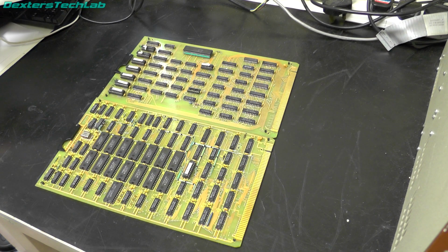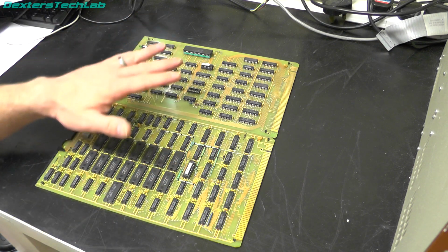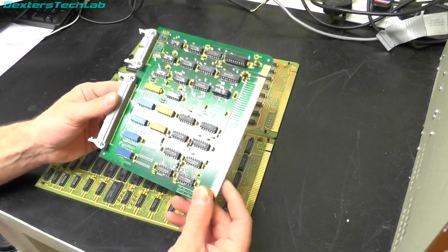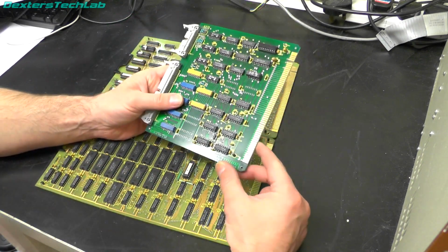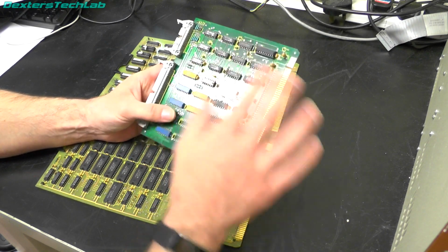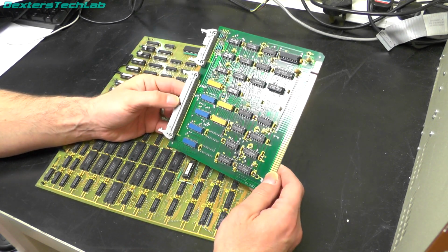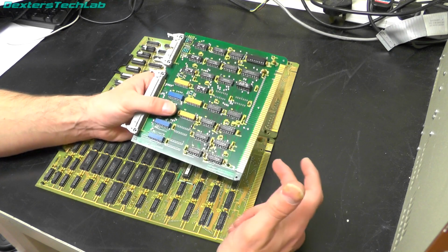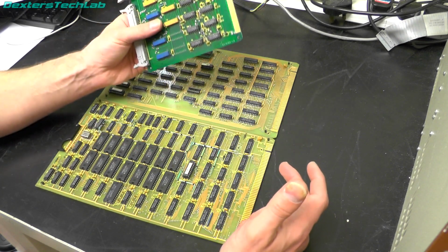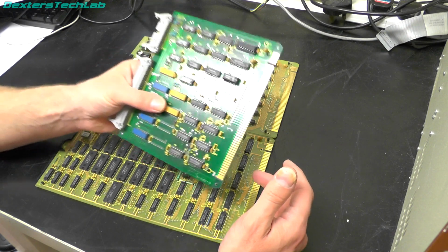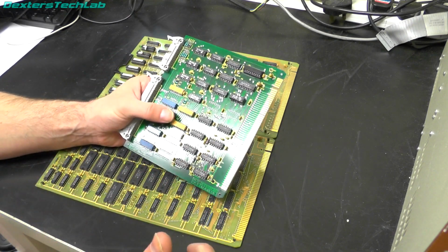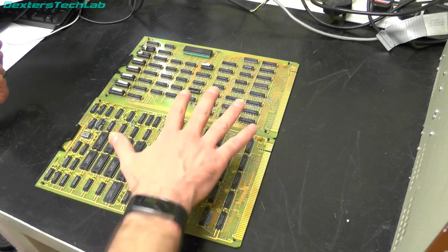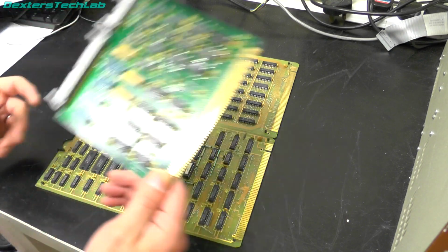Right, so after that rather long intro into the disk formats for the DPB, let's go back to the cards. So we've got the disk buffer and the disk sequencer, and we've got the SMD interface. So the thought has been to actually replace this card here, which is the SMD interface board. This has all of the actual signals on that we need because they go out to the drive. We don't want to mess around with SMD signaling because it's all ECL and that's just horrible to work with. All we want to do is get the actual data that's coming off these cards, which conveniently comes onto this one.